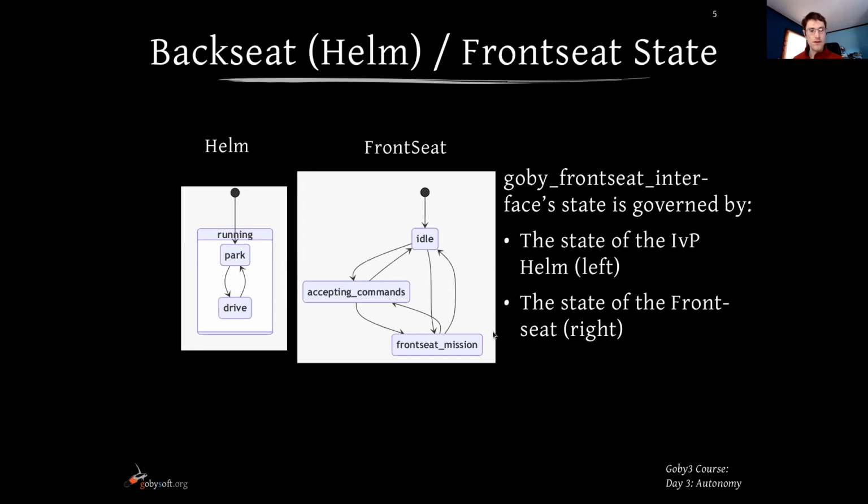And it's also intentionally quite simple. It's either idle, which is powered on, but not in a mission. It's in a front seat mission, which means that the vehicle is under the control of the front seat computer, in other words, the manufacturer computer. And the payload might be listening for data at that time, but it's not in control. And then accepting commands is when the front seat is accepting payload set point commands.